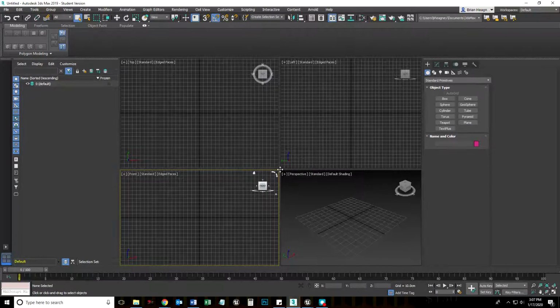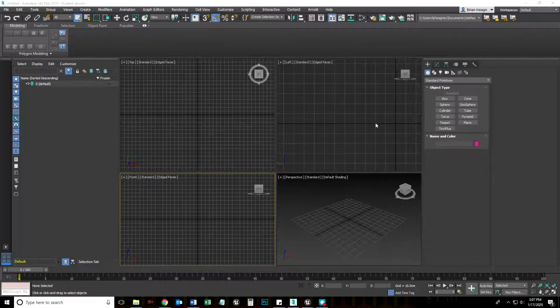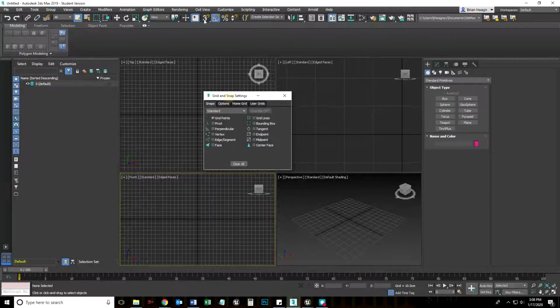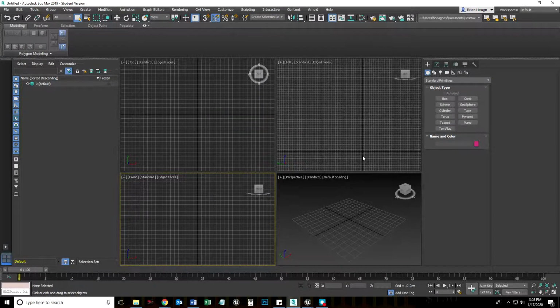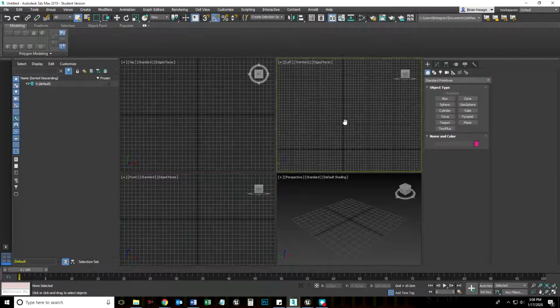Okay, that's perfect. I am also going to check what the size of my grid spacing is. So I'm going to right click on the 3D snaps up here, the snap toggle, go to my home grid and see that grid spacing is 10 centimeters. So roughly 15 of these is 150, because 10, 20, 30, no, that's 100, so 1.5 of these, yeah, 150. I just want to roughly know how large my grid is when I zoom in and out.